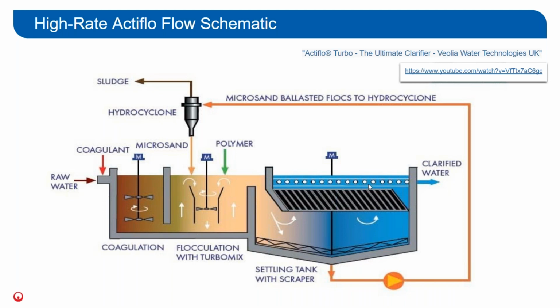This hydrology, or the hydraulics, as well as the chemical treatment, is what makes the Actiflo go, as well as recapturing what is essentially waste, the sand and sludge, into that sludge loop before using that centrifugal force, the hydrocyclone, to scrub the sludge and recycle the nice fresh sand for the retention of that sand that you had bought however many months before.